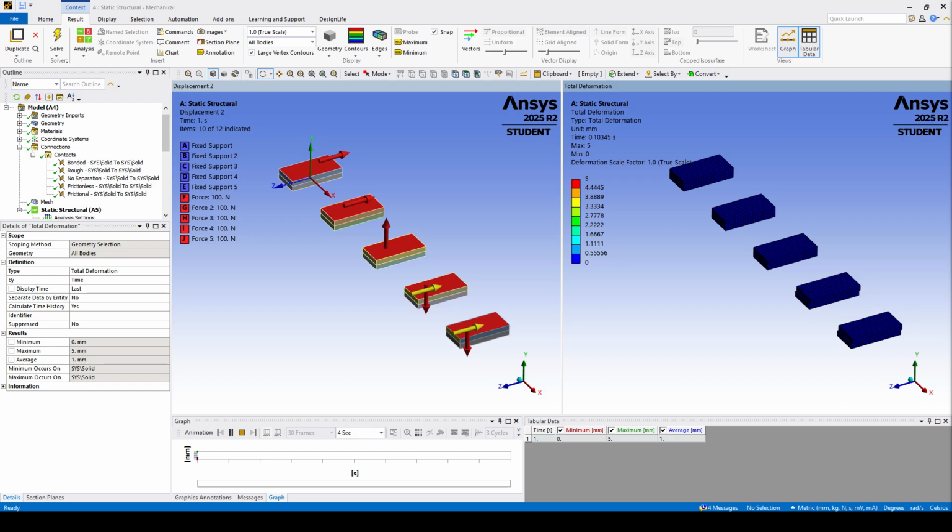But before we start, in finite element analysis, defining how parts interact with each other is critical. By default, parts inside an assembly do not recognize each other's physical boundaries unless a contact region is specified. Choosing the wrong contact formulation can lead to catastrophic convergence issues, false mathematical penetration, or inaccurate stress results.